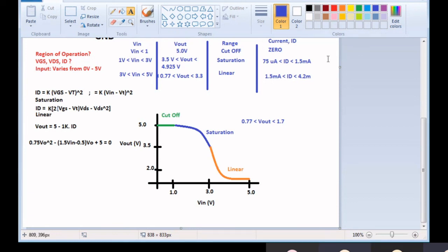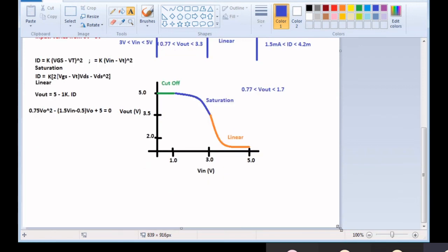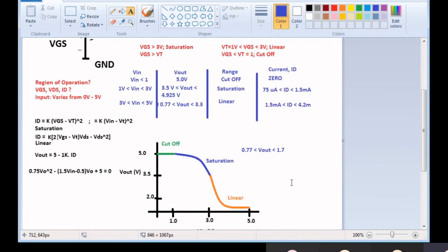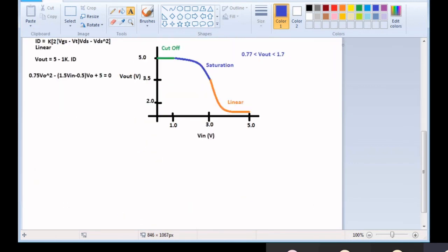Yeah, this is because the drain terminal is at a very high potential in the initial stage. Thus, once the device turns on, it goes into saturation instead of going into the linear region. Exactly. Very good, so that is the correct answer. That is the intuition that you need to get: sometimes your decision making is not limited by only one variable. There are other variables that also affect.